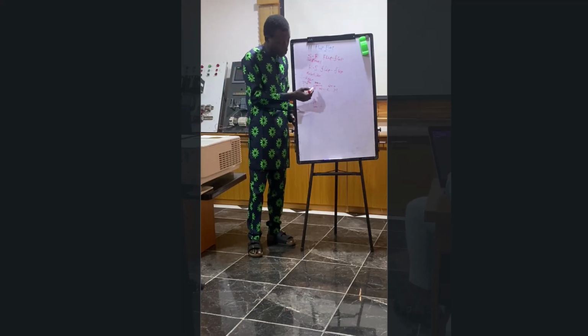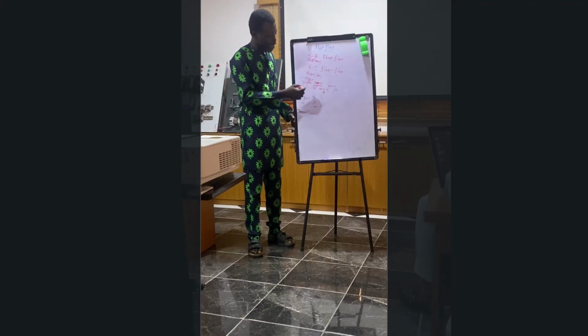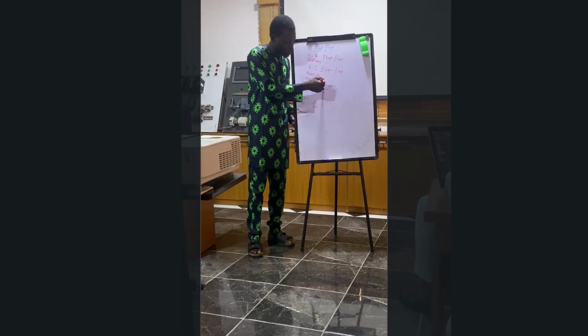Okay, so it will be such that when you press this button, this particular output will become set. That is, this will be equal to what? 1. By implication, the RLO at this point too will be 1. Okay, the RLO at this point too will be what? Will be 1. And it will remain 1 until this is pressed. So until you press the reset button, this will remain 1.